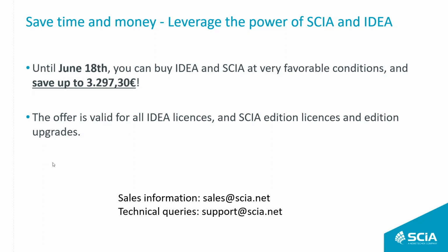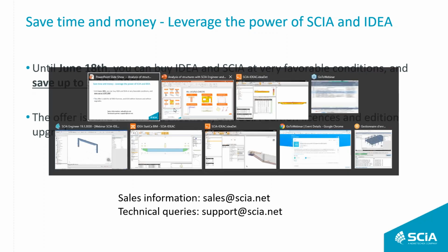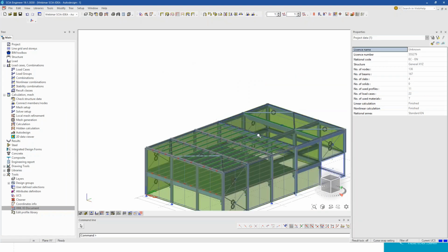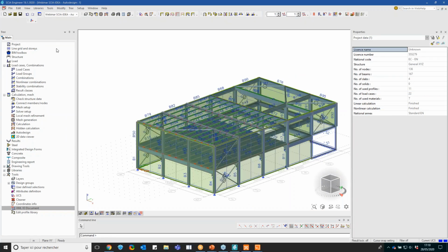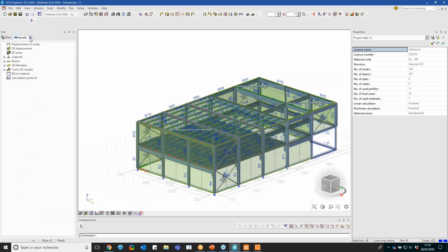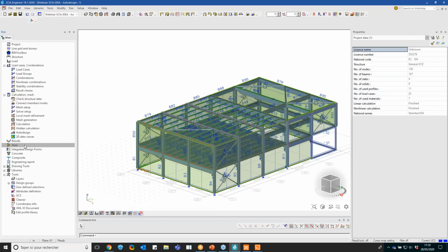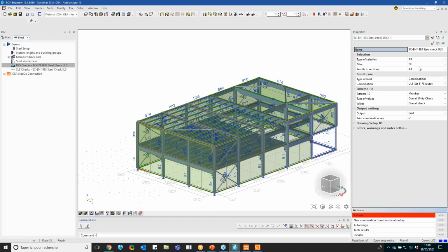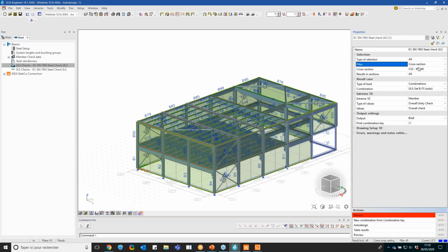Yes, there is. You can always in SCIA have a look at the most, let's say, important combinations. Typically for the linear calculation, the combination is quite quick. We have seen it a little bit before. If needed, and if you have really a lot of combinations, you can go through, for example, one cross section.